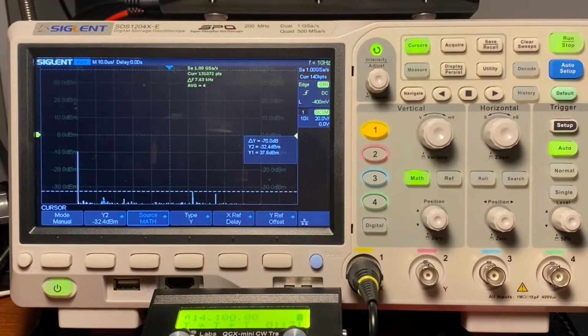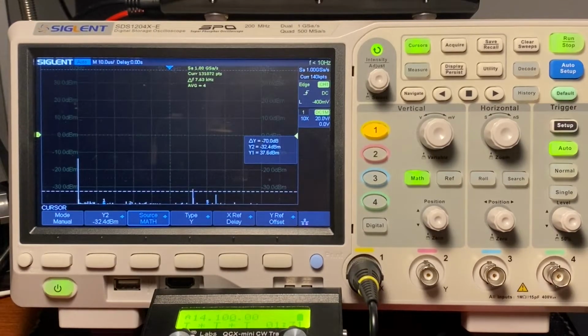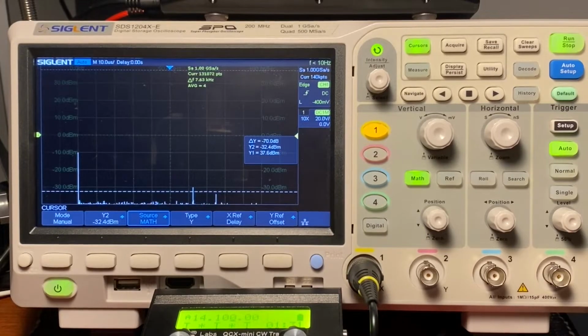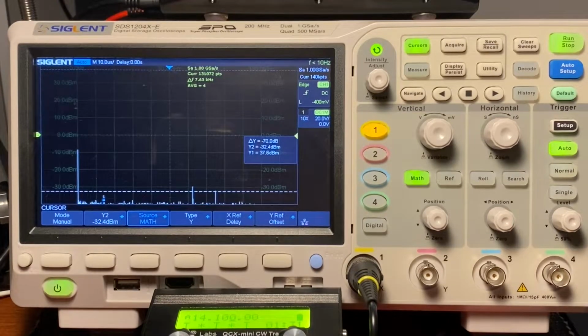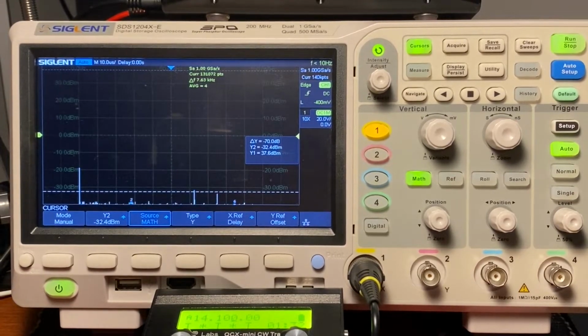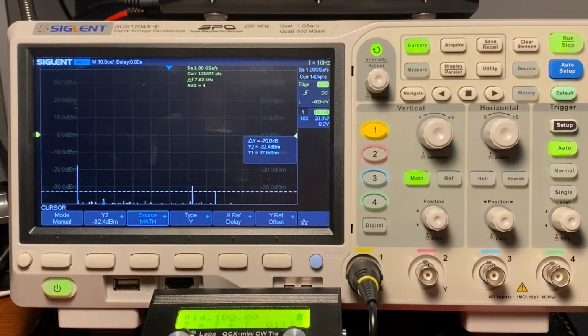These spurious signals generated in the measuring equipment and the noise level that you can see down at the bottom of the screen ultimately will determine the range of our measurement accuracy. We're getting approximately a 60 to 70 dB range that we can rely on here. The noise level is about 80 dB below the carrier, and you can see it moving around a bit. If we average longer, we could get a slightly more accurate indication from it. But basically, it's what's going to set the dynamic range of our measurement.